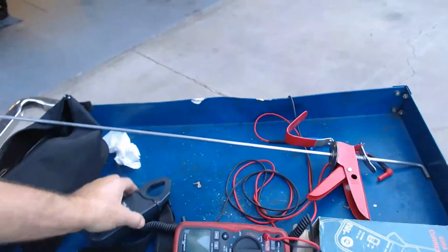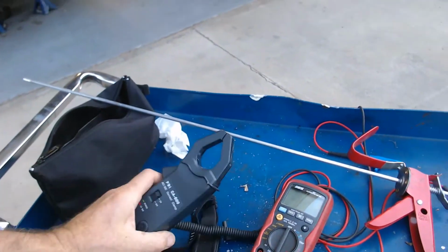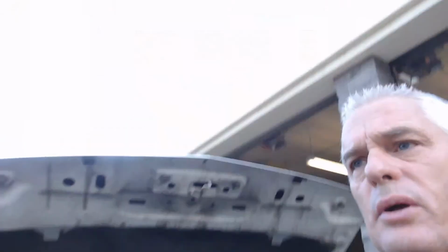Modern cars aren't going to let you load test it with this. Modern cars are going to shut down the alternator, because the computer sees all this current going out of the alternator, it says, "No, I'm not doing it." Shuts the voltage regulator down, doesn't let the alternator charge. So in that case, we have to use that voltmeter with the inductive lead that we have here. We've got to use something like this and follow ProDemand telling us, okay, you're going to have to hook this guy up. You turn on the headlights, run it at 2000, turn on the AC, and decide where it's at. Okay, so that's charging system voltage.